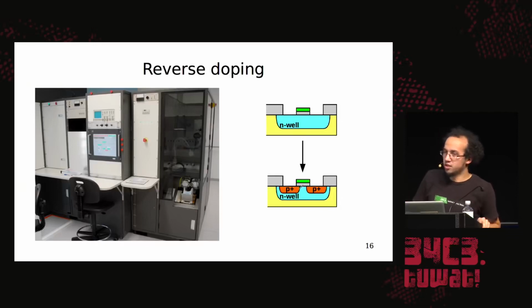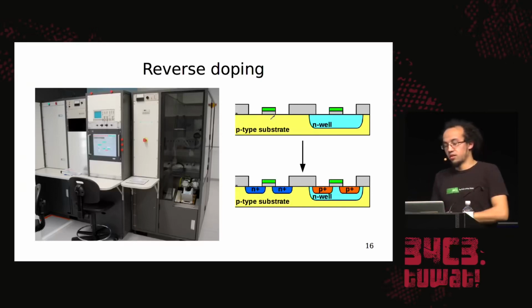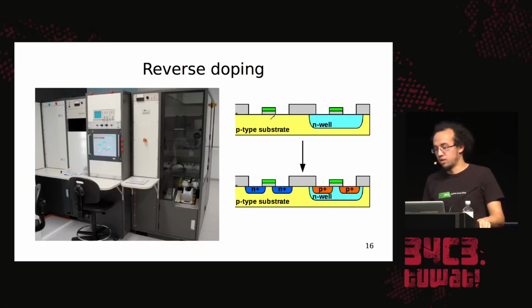And that's because there are two types of transistors inside the chips. These are complementary, so they use either negative charges or positive charges to conduct current. And that gives you the possibility to actually switch things. Otherwise, you'd have just turn on, and you need something to turn it off, and that's the complementary transistor.